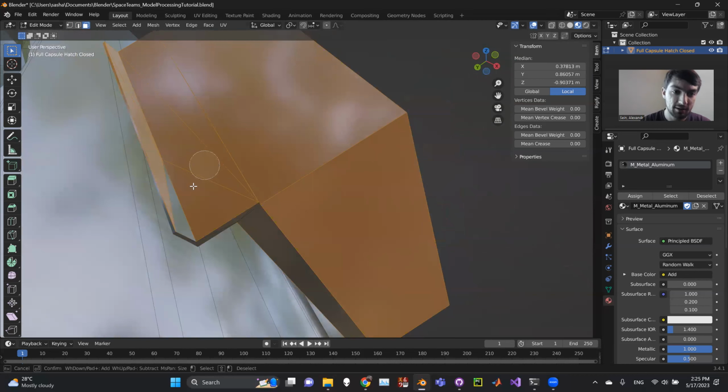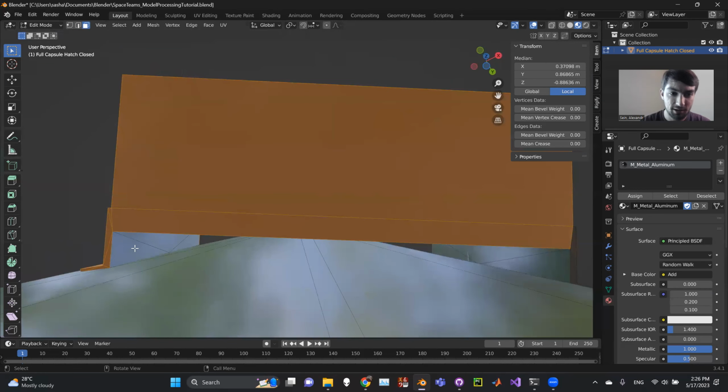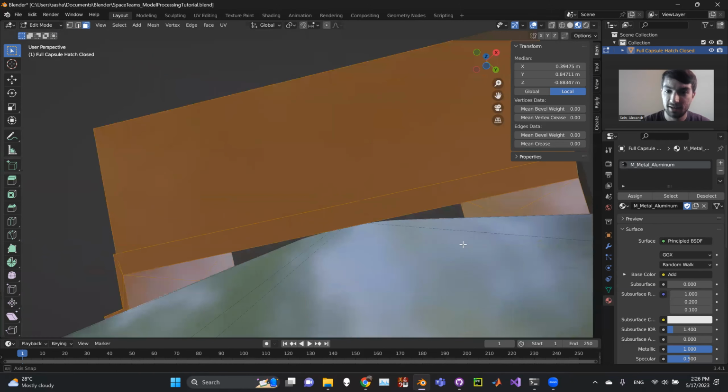Again, hit C, left click to draw stuff. And let's say we want to select all this, but oh, we got an extra face. We don't want that. Middle click and then hold the middle click to draw erase like this. And bring that back though. And let's keep going. So as we go, see there's a couple of faces on the inside. Let's bring up the circle select again. Let's get those. Make sure we get those on this side.